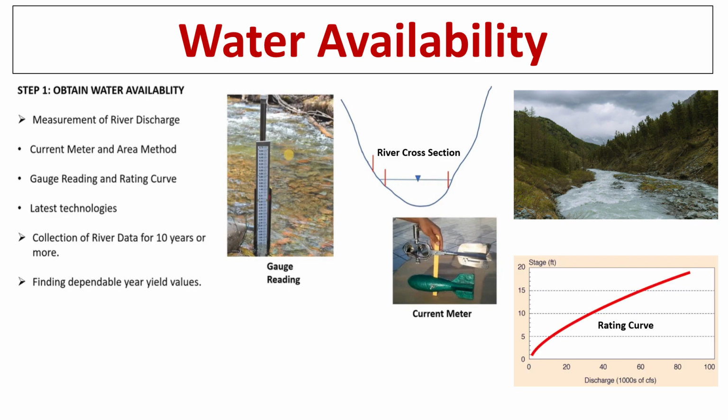Now we have to use the rating curve. A rating curve is nothing but a plot between elevation and discharge. That is, when water is flowing at a particular level, what is the discharge. We can see the rating curve graph here. For any river length or river stretch of consideration, we can develop this rating curve using simple calculations. This can be developed using HEC-RAS software also.